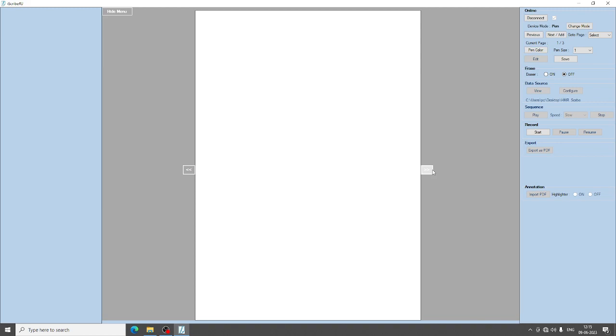In the cascode current mirror, we have different types of configuration, one of which is the wide swing cascode current mirror. So here we have the same 4 transistors M1, M2, M3 and M4, and the gates of the base current mirror and cascode devices are not the same.